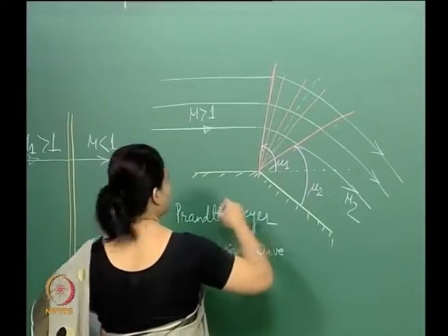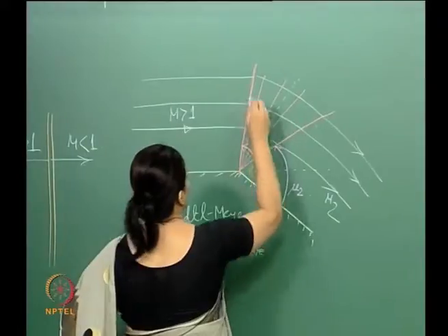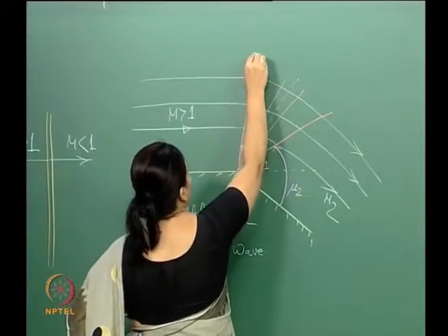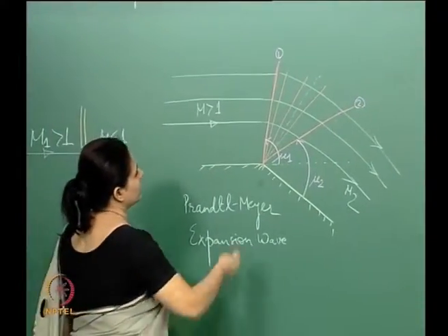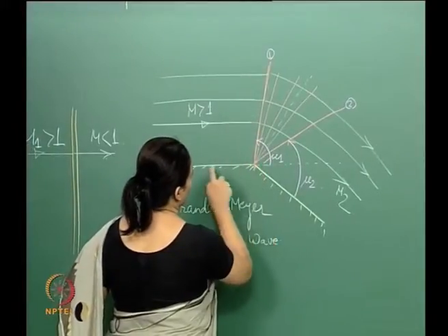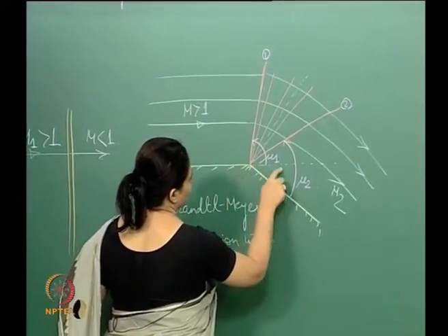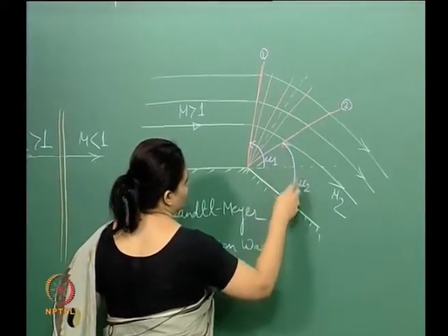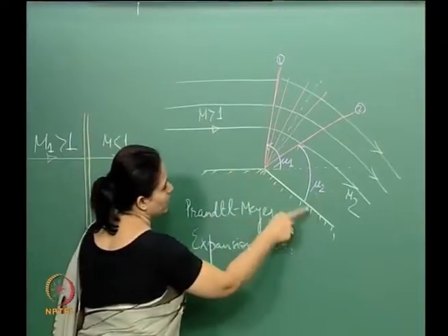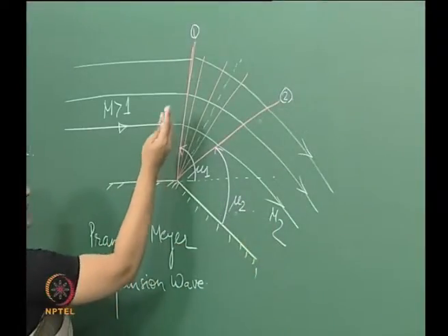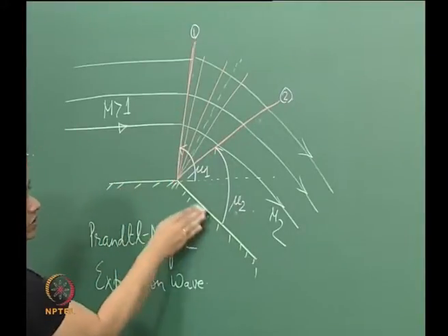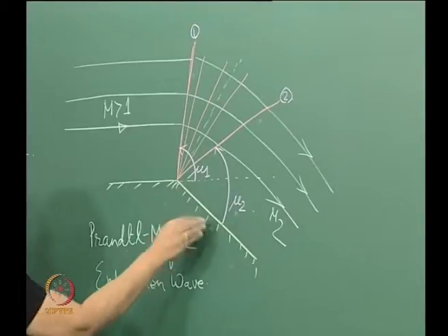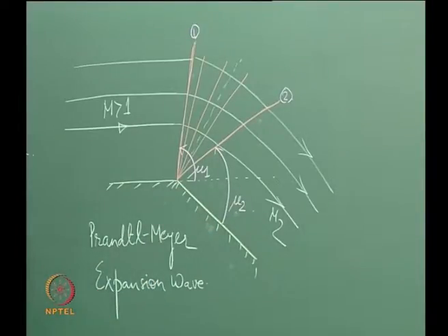So, let us say this is 1 and 2, right. The starting Mach wave is making this angle with this surface, and the end Mach wave is making mu2 with this particular surface, because what you see here is that this Mach wave is here in the surface, and then it expands, the surface has actually changed, which is this. Therefore, we take the angle with this surface here. So, this is essentially my Mach wave.